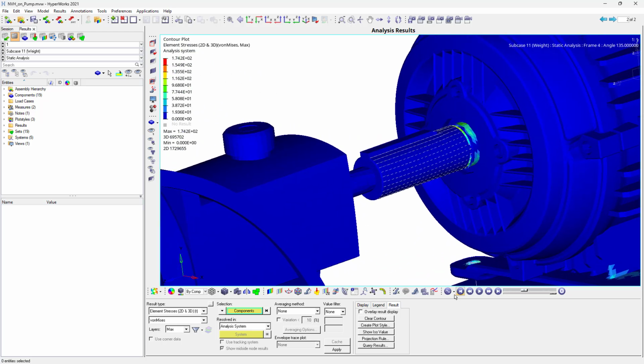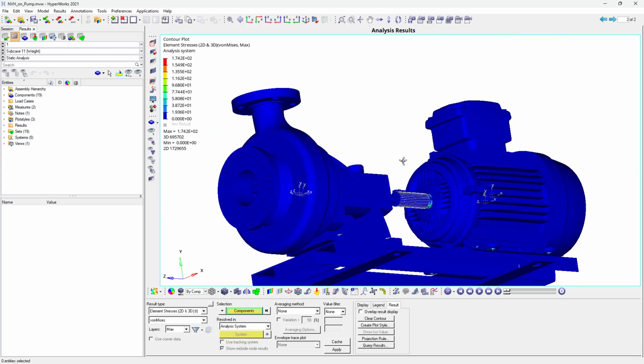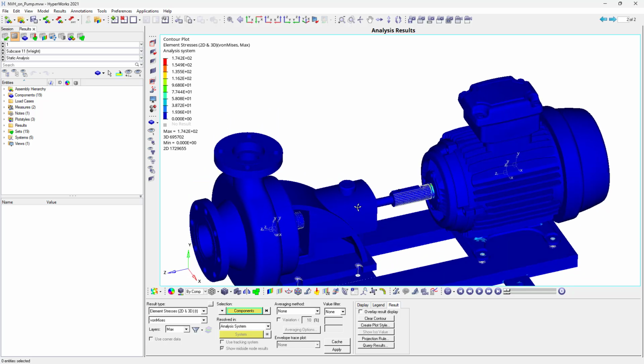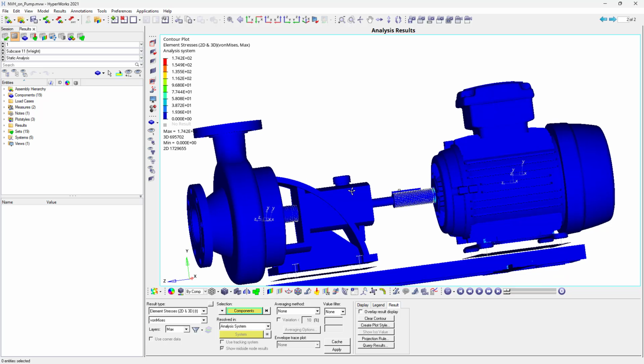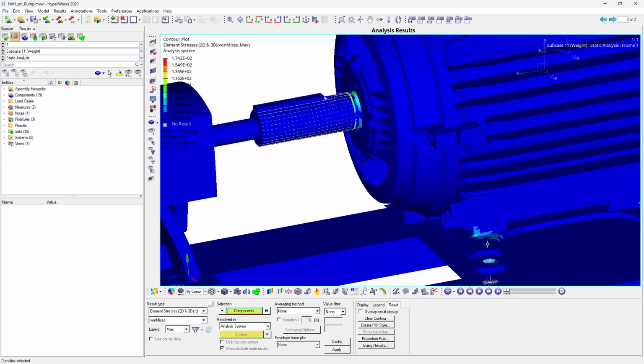Because the whole load, the Newton which we have defined in the form of mass, is impacting on those RBE2 locations only. So if you had selected RBE2 for the whole model, then you might not be having this one. So yeah, very important. While you define the boundary conditions, you should take it properly.